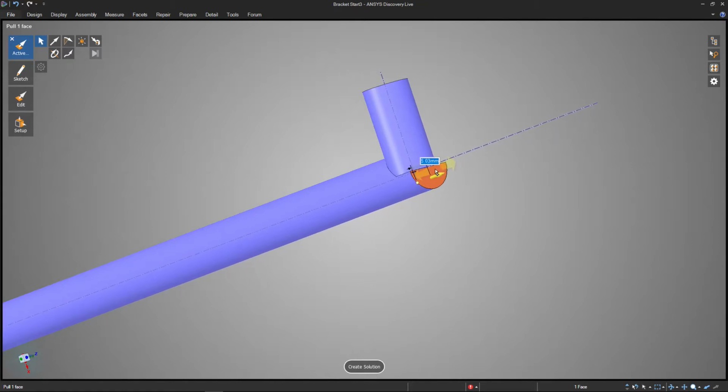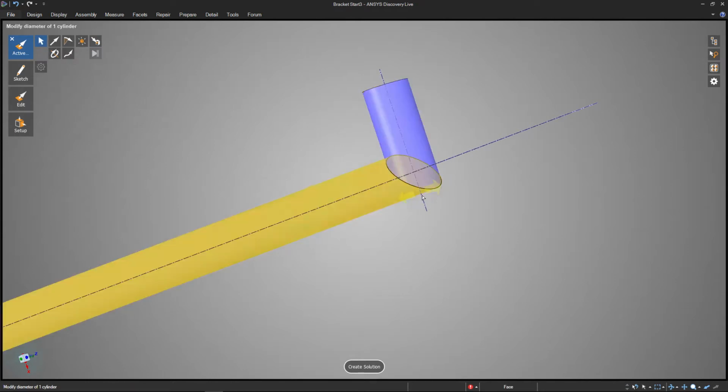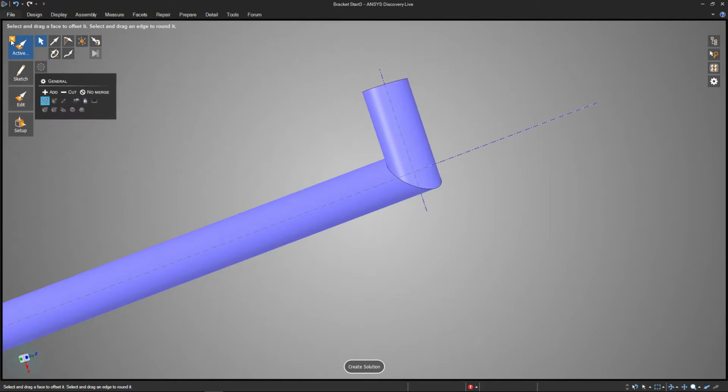It kind of knows that I want it to be cut out from that top shape, but it's a little hit or miss here. So we've got some extra tools in the pull option here. If you click on it and you get the menu that pops up, we can do the pull up to tool, and I'm just going to click on this face then. And so it pulls it right up to this intersecting cylinder there and makes a real nice looking finish.